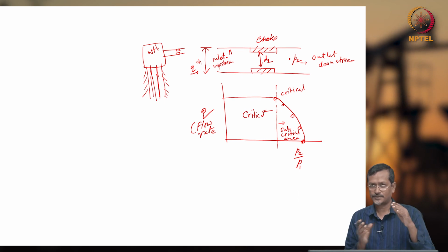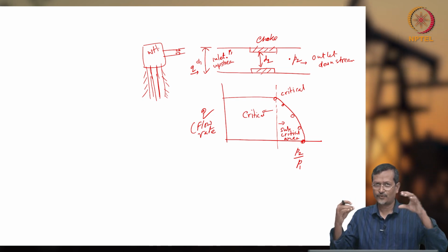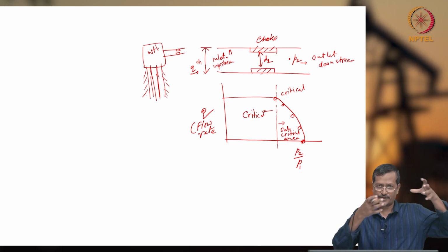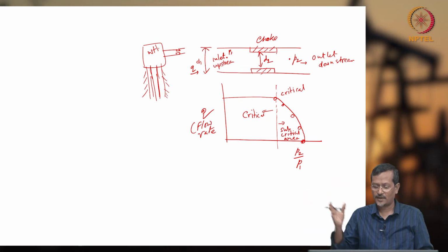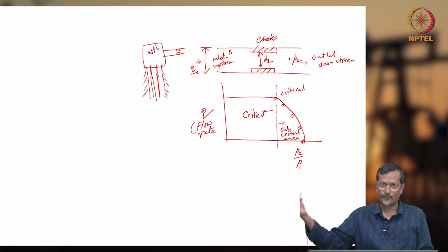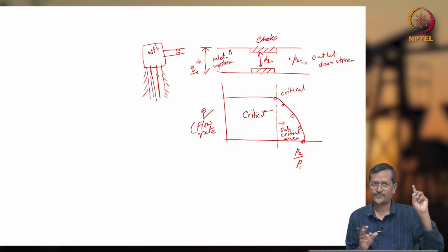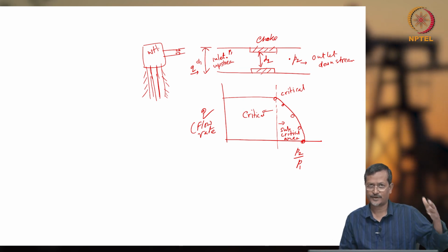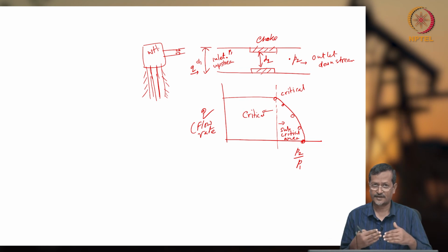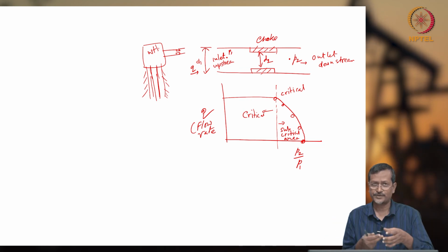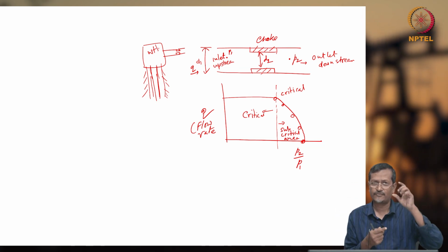Now once, let's say, you have one choke running under critical condition, if you change the P2 pressure, your flow rate will not change actually. So your reservoir and the whole restriction will have the same resistance, the same flow rate will be maintained, but after the choke, whatever pressure you are trying to play with, for example your separator system changing or anything you are doing, upstream will not get affected. Because if upstream, or wellhead and wellbore and reservoir, get affected, there can be multiple problems. One can be gas coning, water coning, more sand can come, debris can come, or some blockage will be there, artificial lifting system can fail, or some valve can fail, wellhead, so there will be multiple issues.